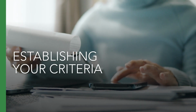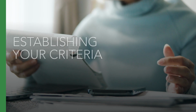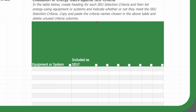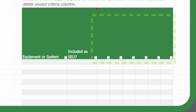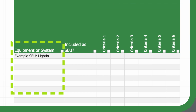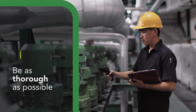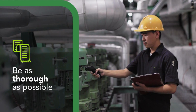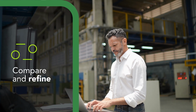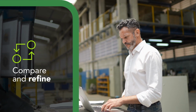Now that you have a documented set of criteria, you can begin to evaluate your systems and equipment against them. Use the table below your criteria list in the SEU criteria evaluation sheet of your workbook. Copy your criteria into the column headings and list all of your energy-consuming equipment or systems in the table. At this point, it is good to be as thorough as possible to make the process comprehensive. Seeing how all your equipment and systems stack up against your criteria can also help you refine the criteria later.